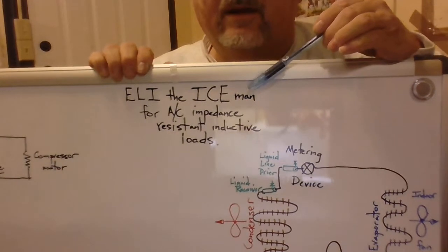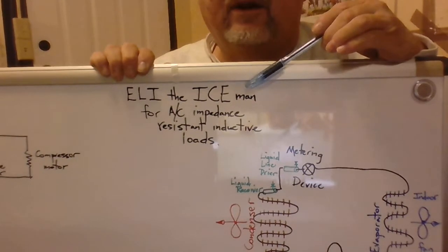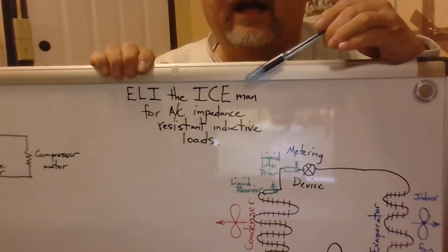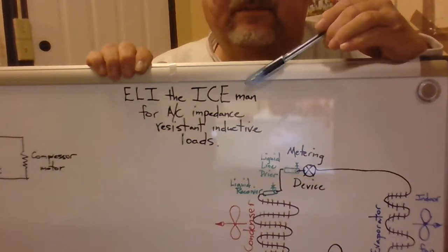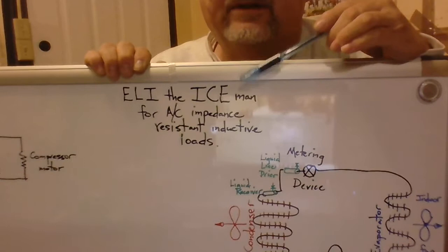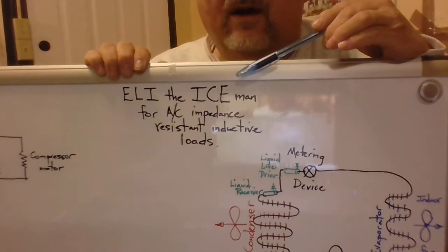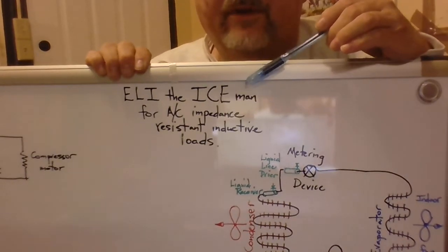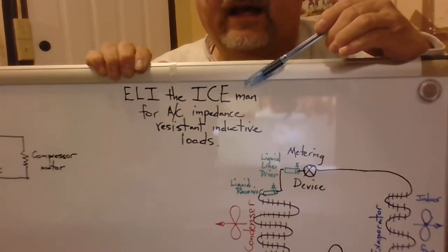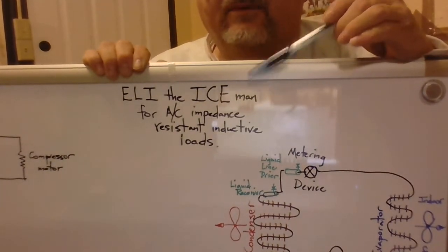Once again, you've got to remember that pressure difference creates current flow. Resistance is like pipe flow in water. Without a pressure difference in water, you cannot have flow in a pipe system, so you need an elevated water tank or a pump to create that kind of pressure difference. Once you do that, how dirty the pipe is determines how much water flow you're going to have. The same thing happens with current flow, and this helps you begin to understand that, because as the pipe resistance becomes greater and greater with time, the water flows less.